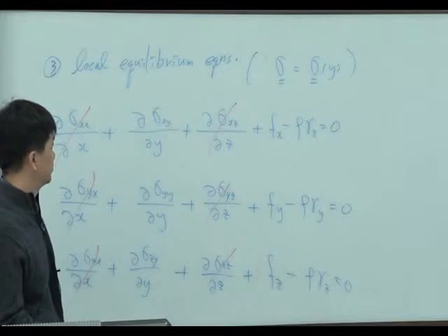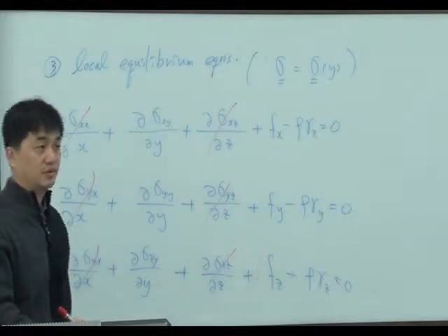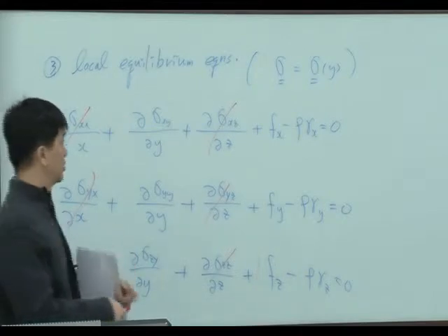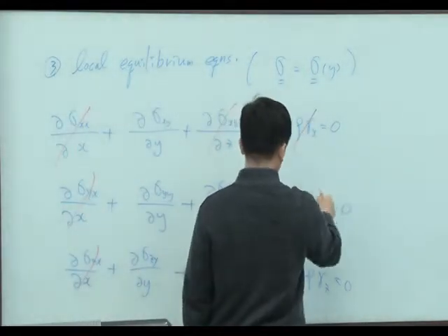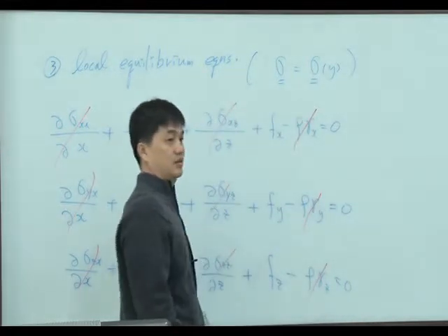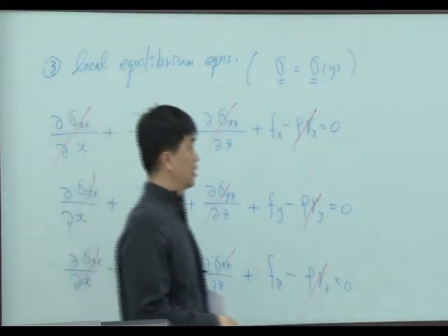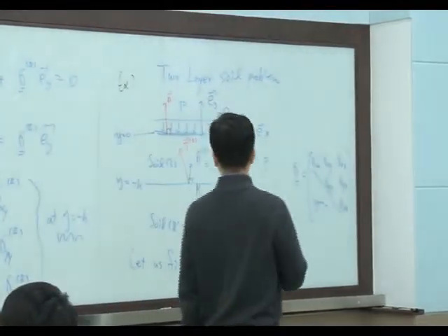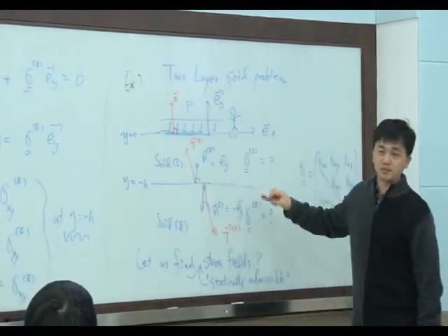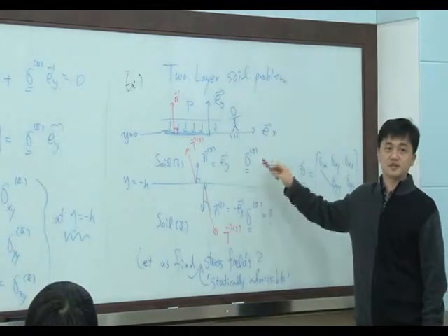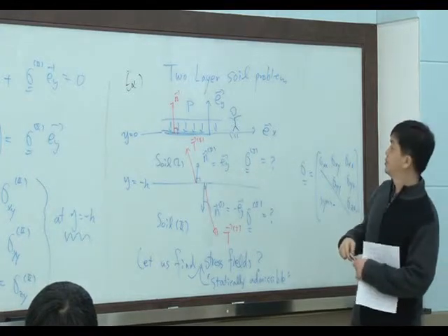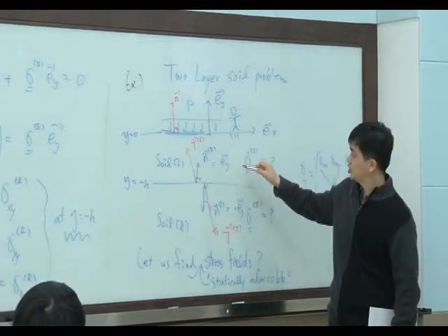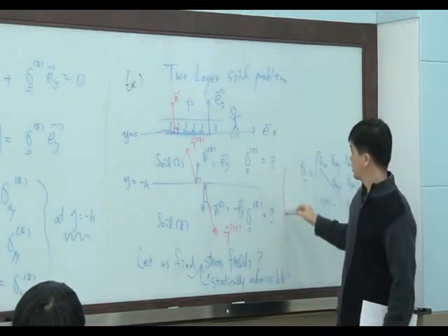And also, is this a static problem or a dynamic problem? Static problem, right? So we don't need to consider this dynamic term, acceleration, right? And now let's think about the body force. What kind of body force is applied here? F. What's the F? Here, gravity, right? G will be applied. Gravity load, G.